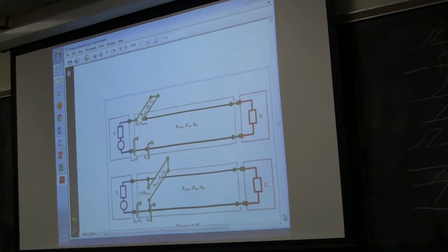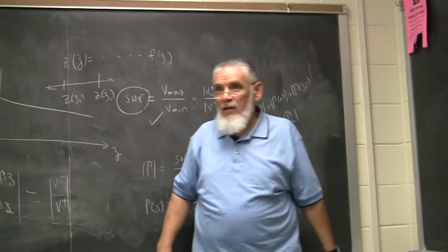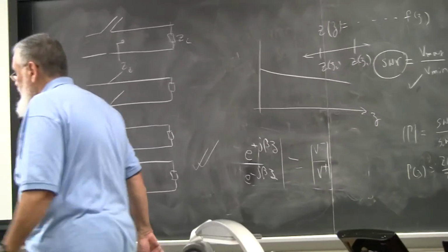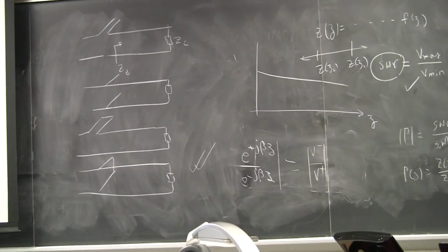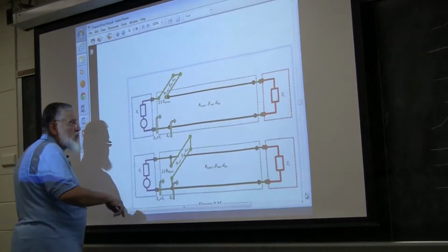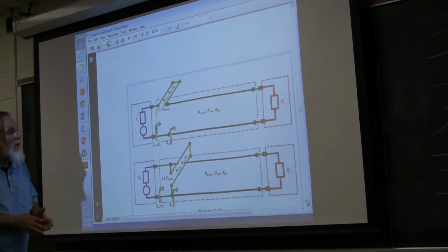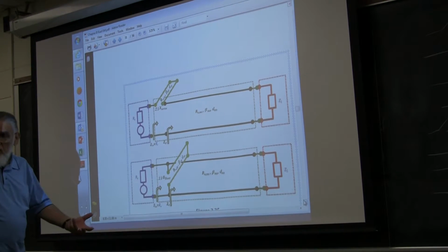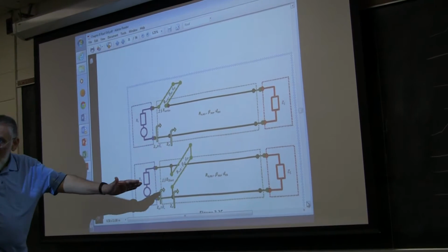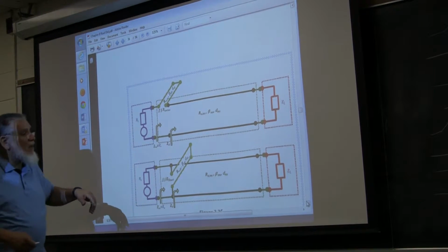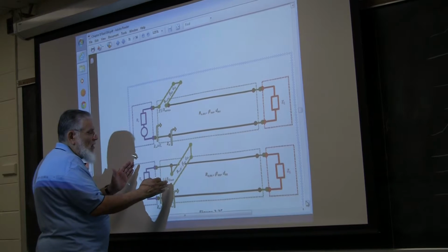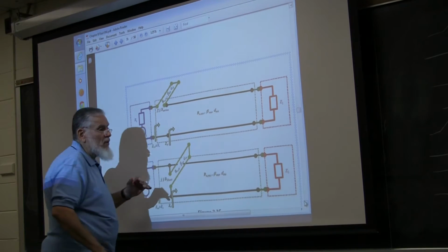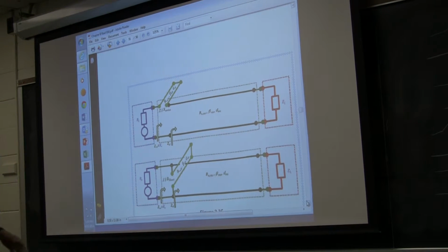So the majority of your line is matched, and you are drawing the most signal out of your source accordingly. Now, if there is a particular application where you'd like to do the opposite, then you do your calculation from the other side. Then you start here and you try to make the impedance match to the load in the opposite way and minimize the distance where it's mismatched.